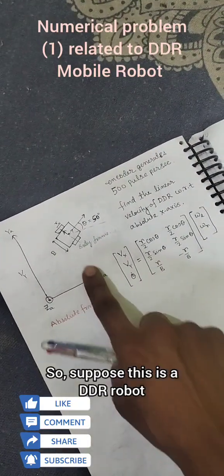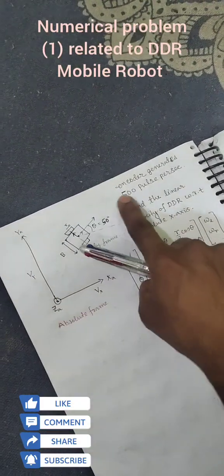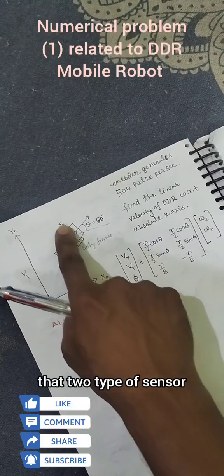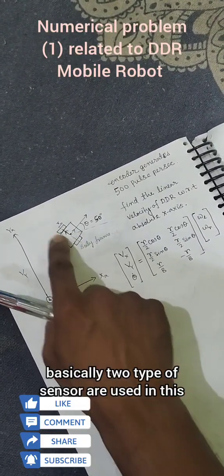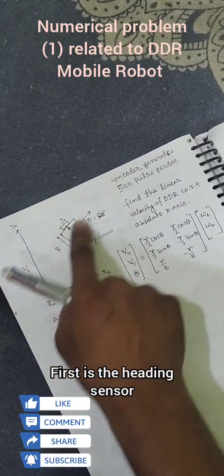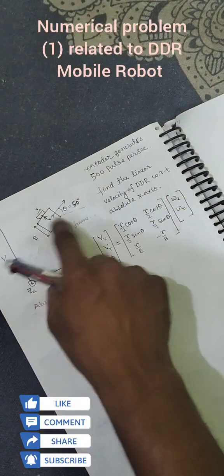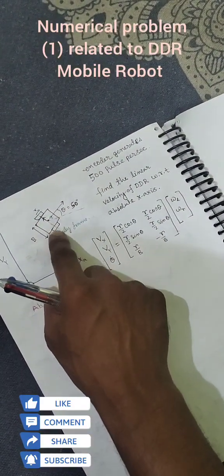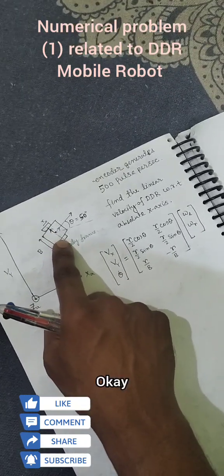Suppose this is a DDR robot and this is the absolute frame. As I talked about in the last class, two types of sensor are used in this DDR robot. First is the heading sensor, which gives us the direction of the robot, that is theta, and the other sensor is the encoder. An incremental type encoder is used here.